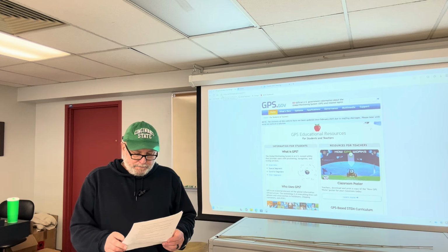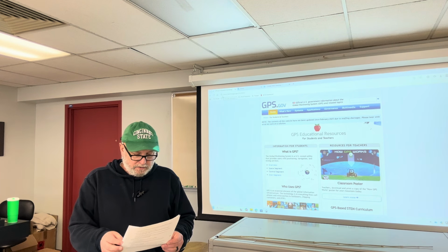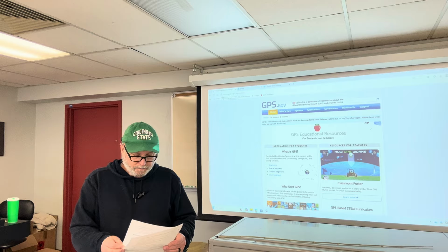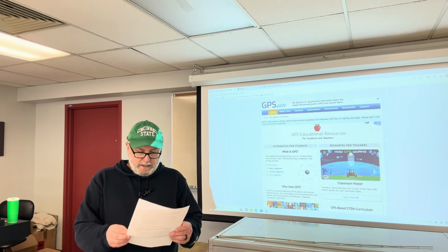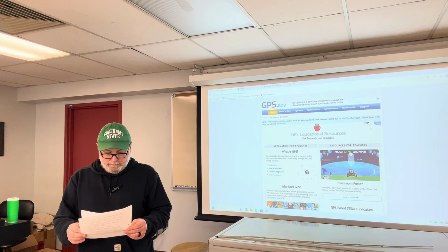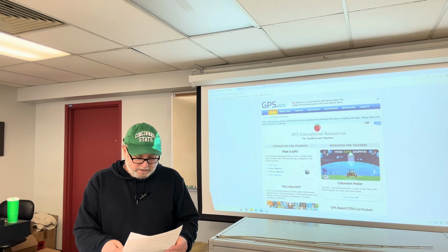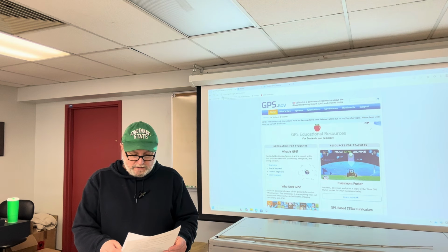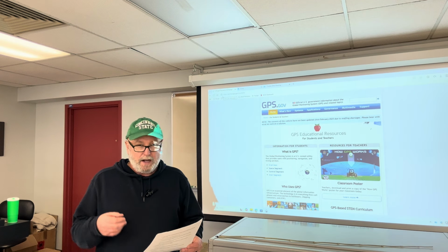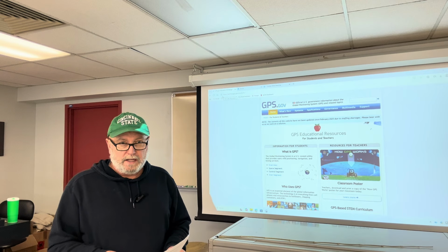Let's see, relating errors to accuracy orders. The UERE and the DOP are connected with expected horizontal and vertical accuracies. This is how you justify that a given method, occupation time, can meet first, second, or third order standards.